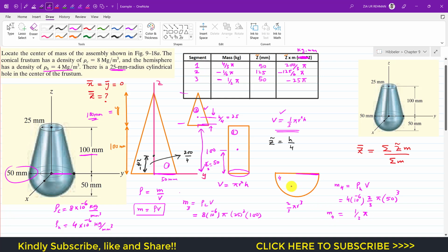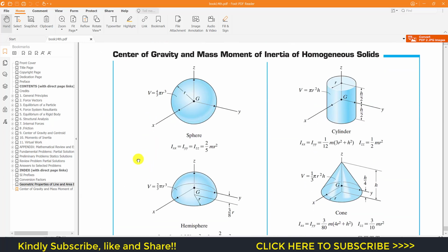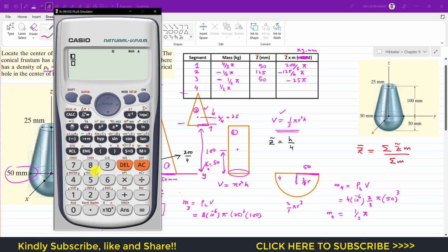So this is the mass of that fourth segment, that is the hemisphere. Its mass is 1 divided by 3 pi. And from the table, the location of the centroid of a hemisphere is at a distance of 3 divided by 8 r from its base. So we can find that, let's say its centroid is located somewhere here. So this distance will be 3 divided by 8 r, and the radius is 50. So 3 divided by 8 multiplied by 50.